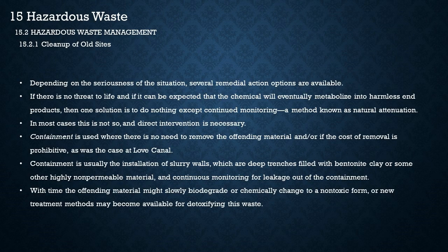Depending on the seriousness of the situation, several remedial action options are available. If there is no threat to life, and if it can be expected that the chemical will eventually metabolize into harmless end products, then one solution is to do nothing except continued monitoring, a method known as natural attenuation. In most cases this is not so, and direct intervention is necessary. Containment is used where there is no need to remove the offending material and/or if the cost of removal is prohibitive, as was the case at Love Canal.